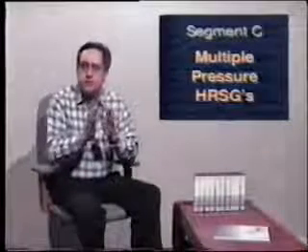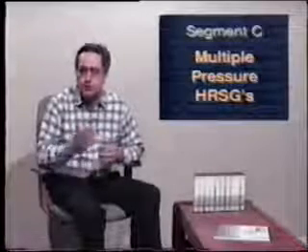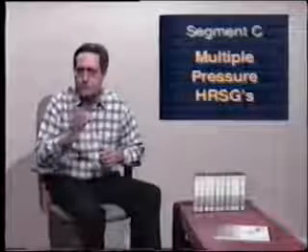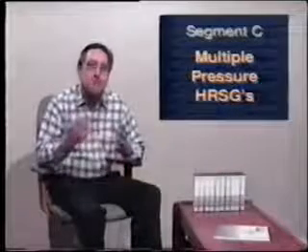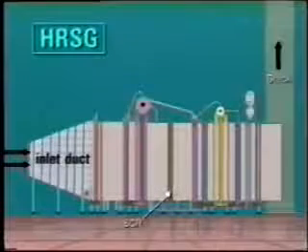One particular disadvantage of using the SCR system for NOx reduction is that it will not be available when the HRSG is bypassed. And this would mean that the gas turbine would need to be shut down if the HRSG was inoperable. Of course, one way around this problem is to install a steam or water anti-NOx system for use on such an occasion.